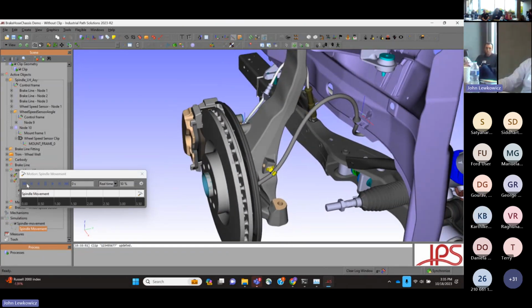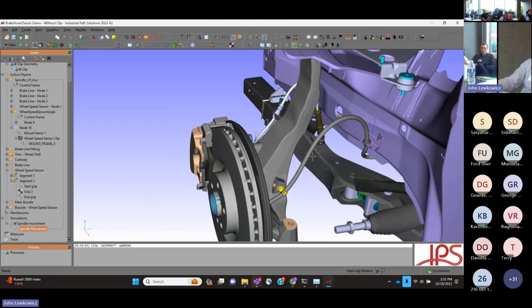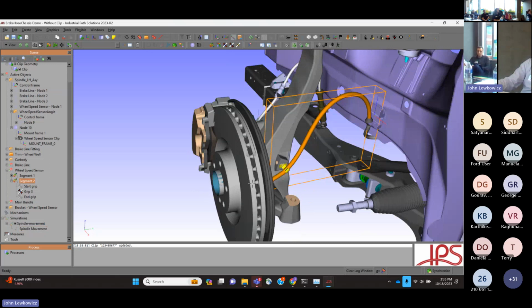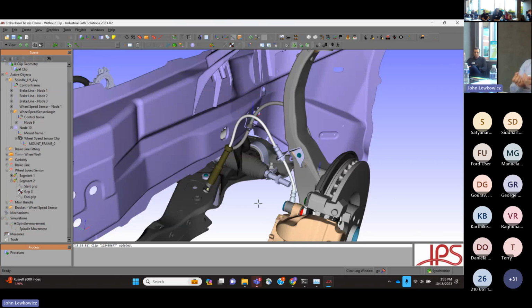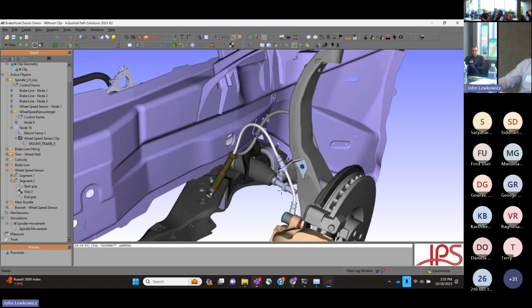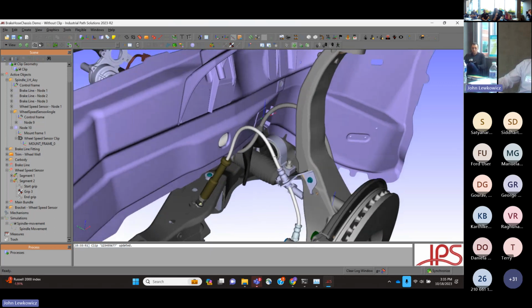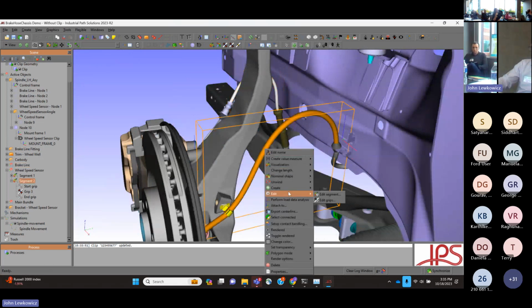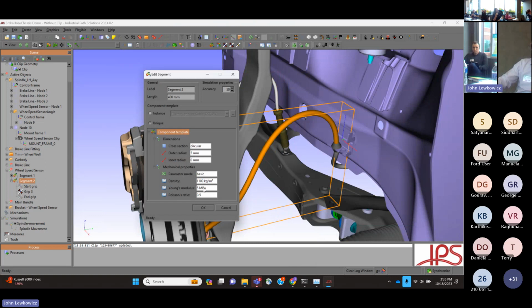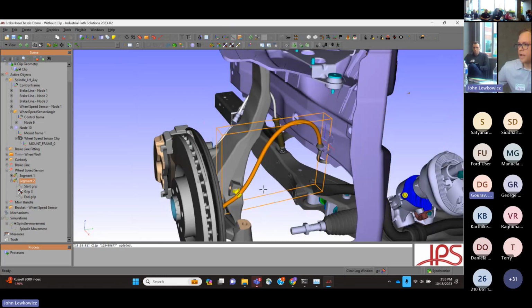Yes and no. It depends on what you're interested in. If you're interested in the shape of the flexible, the material properties are much less important. I mean, they do have some effect, but often you can get a really good approximation of the shape of a flexible using just generic material properties. If you want a very highly accurate result, then yes, you need some kind of material property defined for it. But this one's probably just defined with the generic properties that default in when you create a cable. And I guess it's by default, right? It's default properties, correct.